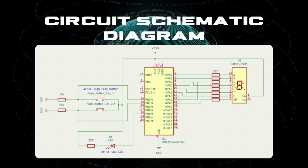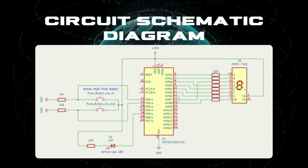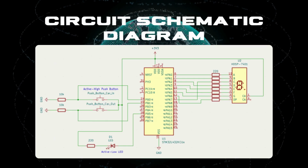Lastly, the output LED connection, which is the green LED, is configured as active low, with the cathode connected to PB5 and the anode connected to 3.3 volt via a 220 ohm resistor.